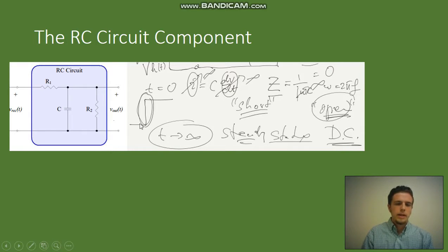In here, we can give it a step response as our Vin, and with this, we gain an infinite slope, basically, and we have our I equals C times dV over dt as before. But with this slope, everything will go to infinity, your I and your dV over dt, therefore shorting the capacitor. And if we look at this from an impedance standpoint, we have 1 over jωC, and ω, our omega value, is equal to 2 pi f, and this frequency is infinite at this point, thus not giving it open, but